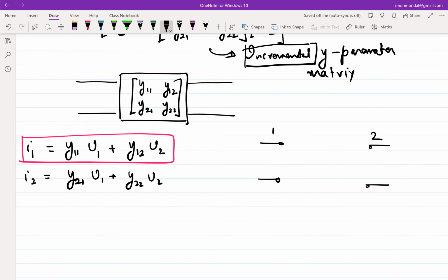So what is the relationship? First relationship is the first term, that is the current that is flowing in. Obviously, the current that is flowing in one terminal is also flowing out of the other. Sorry, this is I1. Otherwise, nothing will make sense. So the current that is flowing in through the top terminal, or into this port, is dependent on the port voltage V1 via proportionality.